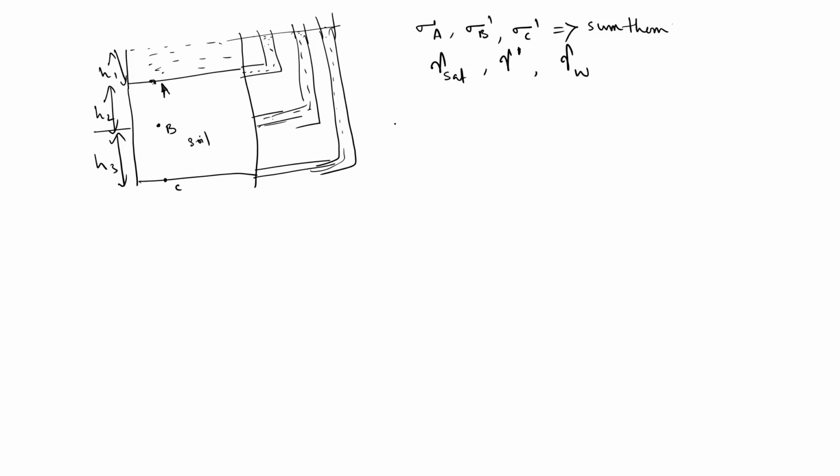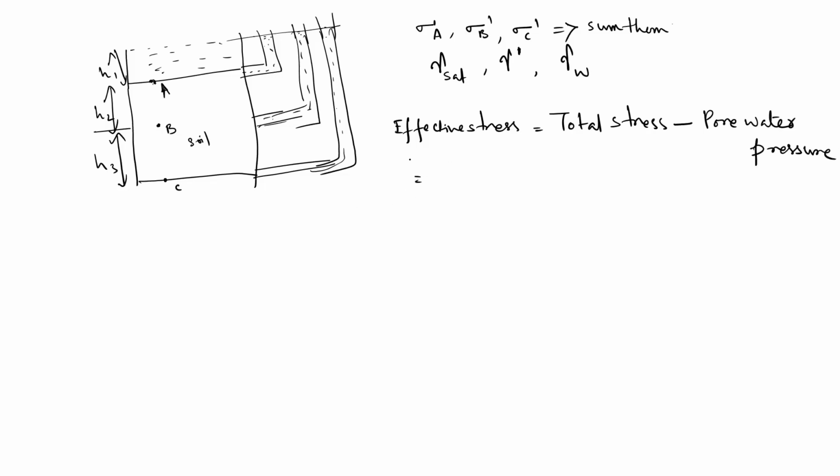First of all, how to calculate effective stress at any point in the soil? It is total stress minus pore water pressure. How to calculate total stress?